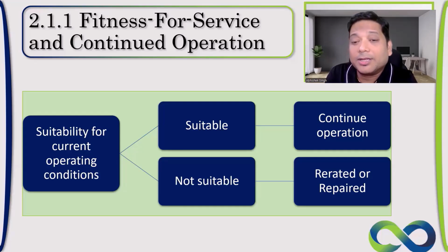So there can be only two outcomes, either it's suitable or not suitable, whenever we are performing FFS. If suitable, continue with the operation. If not suitable, either re-rate or repair.